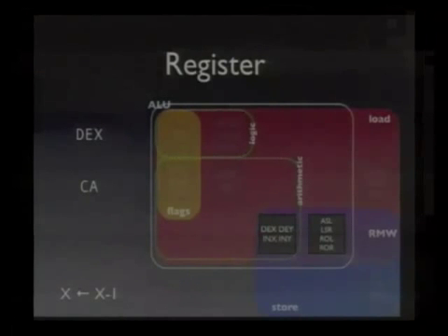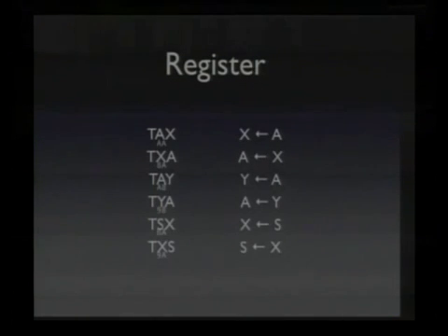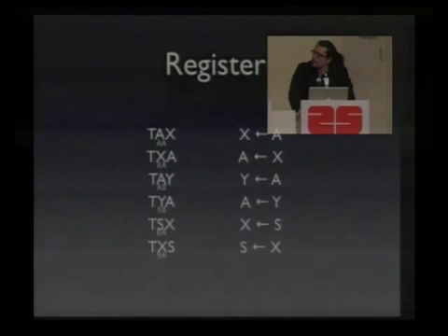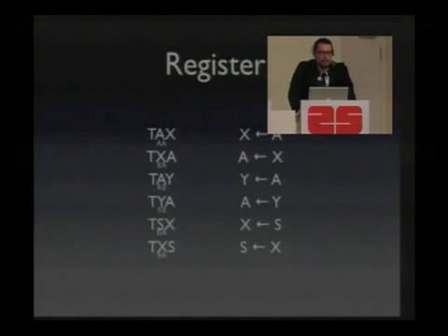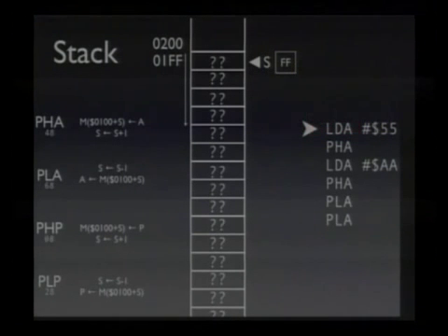And then there's register addressing, for example, the shift instructions for the accumulator and the decrement and increment instructions for registers directly work on those registers and don't need any extra parameters. There are register transfer functions between A, X, and Y, and you can also copy the stack pointer between X and the stack pointer. Speaking about the stack pointer, the stack grows down from 01FF.